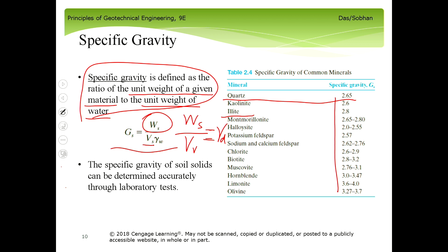Even if it is soft clay, when you change the place the soil is changed. This is why soil is complex: even if you call it by the same name, as the spot changes, it always changes. If the depth is changed, it also changes. But if you have the same soil in the same spot, the specific gravity is definitely constant.